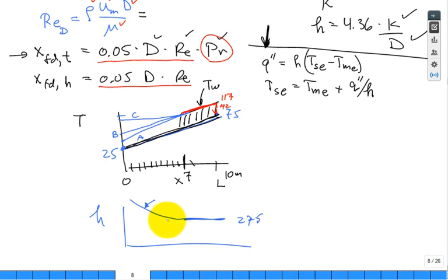So because it's higher, then we look at the q double prime equal to the H times the delta T. This is greater, hence the temperature difference doesn't have to be as large. Hence the right answer is A. The theta is smaller, the temperature difference is smaller, until it's fully developed, and then the temperature difference stays 42 degrees.